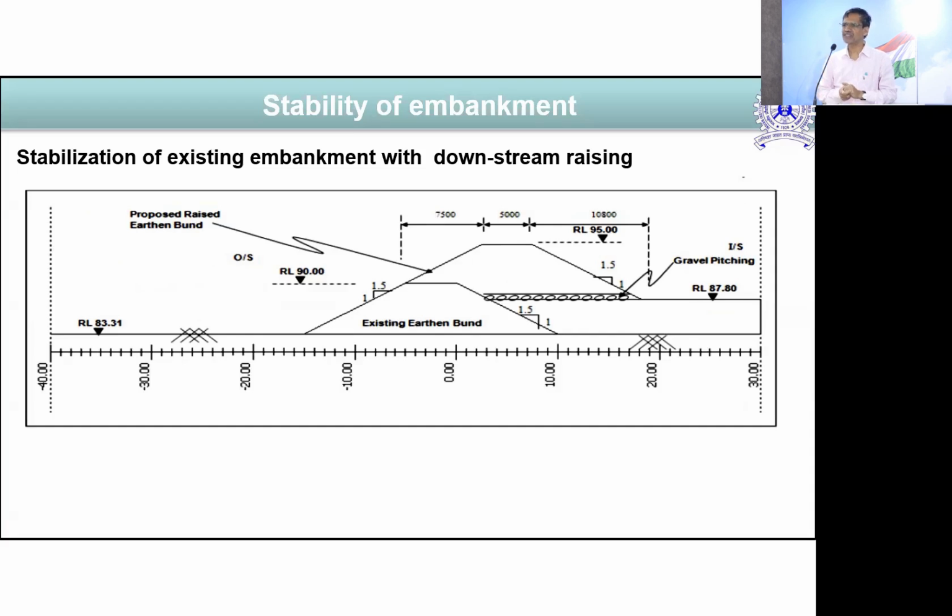So how will you know what is there? Only nowadays, through geophysical exploration, such as MASW, you can get some information. Otherwise, most of the emphasis is on the pond itself, to check the soil, what the bearing capacity is and how much it can take, because I am putting the upstream method on it. But I am forgetting the embankment below. Fortunately, if it is not the centerline method, the load may be less there.